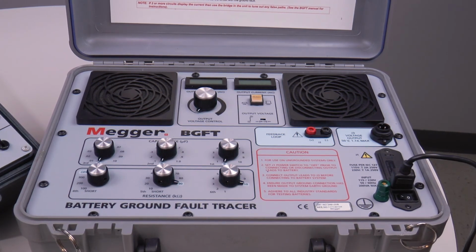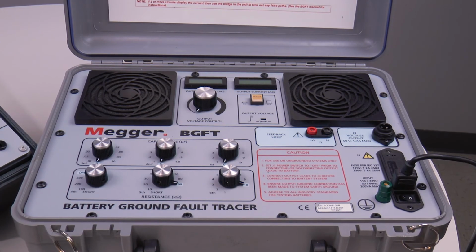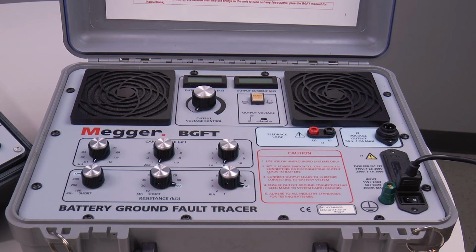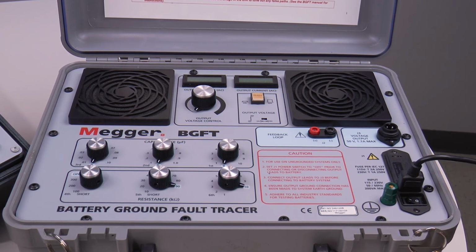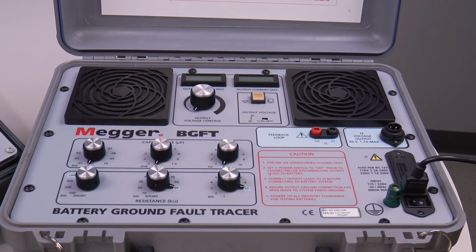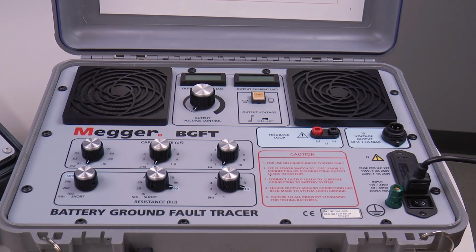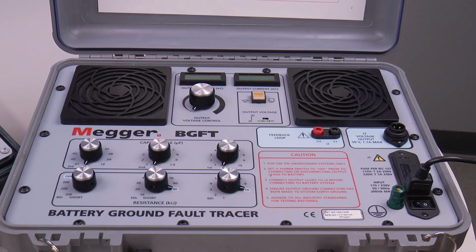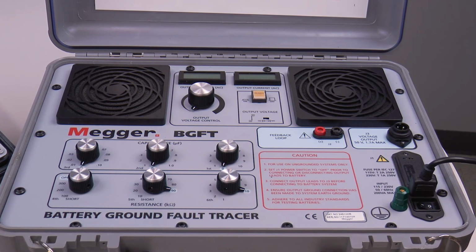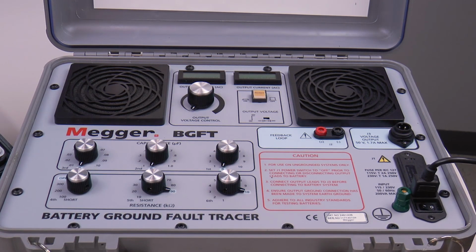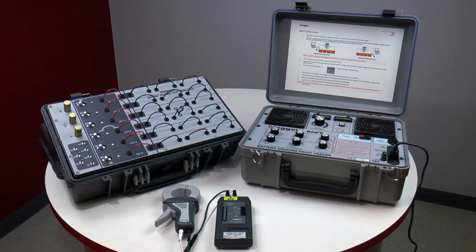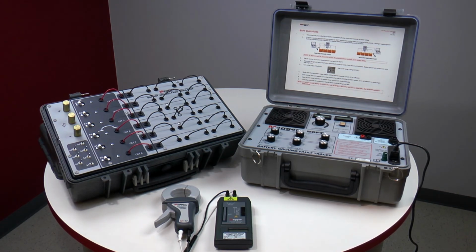We always want to characterize the fault before tracing it. Many times faults will be mostly resistive and we can go ahead and trace them. However, in cases where there are long cable runs, the capacitance from these cables draw leakage current, and this produces phantom faults that can cause us to trace all day and never find it. This is why the BGFT method of characterization will save you